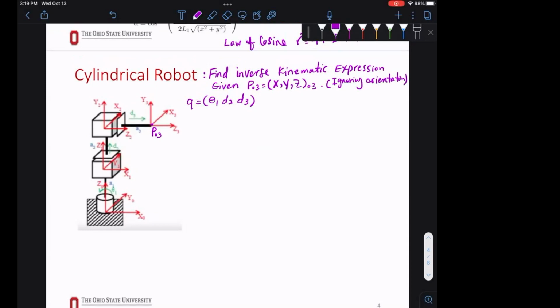This means that right now I'm not caring about theta X, theta Y, theta Z. You can find it from different assignments, right? For now, we're not caring about the orientation, just thinking about the position, to make it simpler. So the first step, we have to identify how many joint variables we have. We've done that. That's always your first step. So I'm going to say step 1.